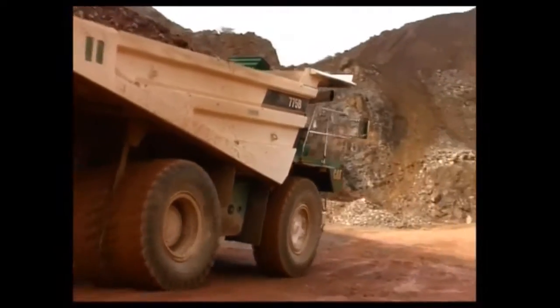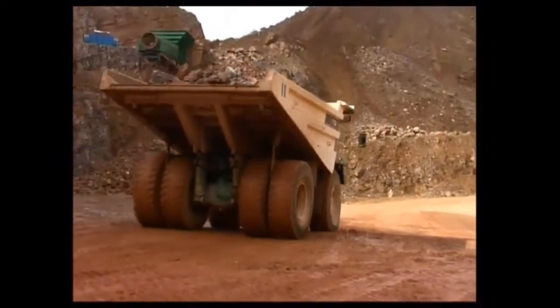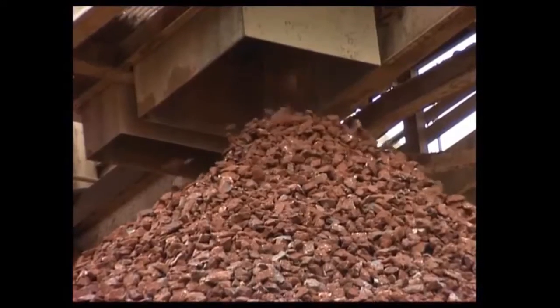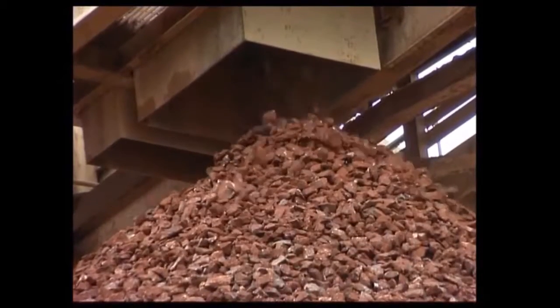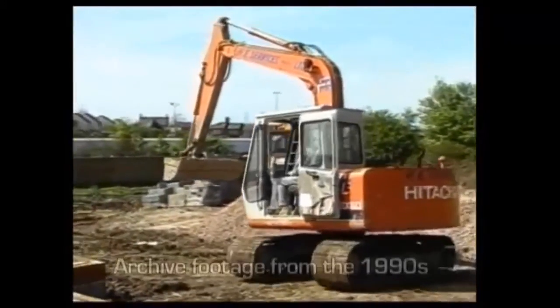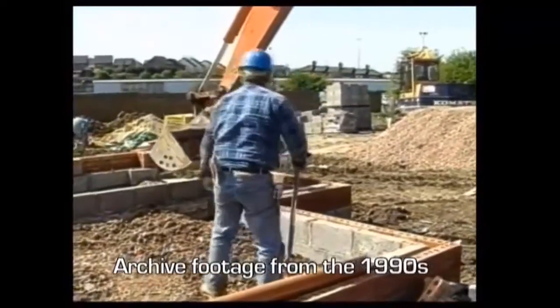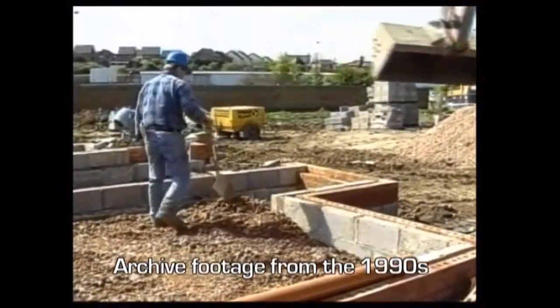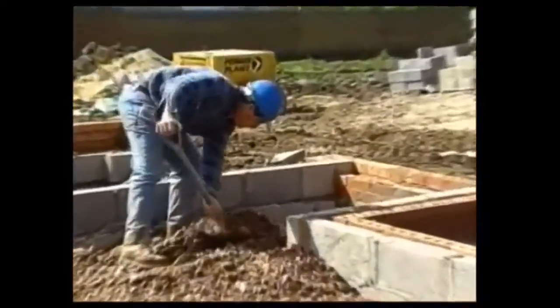In some parts of the country, stone is not readily available and other materials have to be considered. In the past, broken bricks, crushed concrete and various industrial and mining wastes have been used as hardcore. These materials should be used with caution, however. Some may contain impurities, which over a long period can react with water, causing expansion of the hardcore or a chemical reaction in the concrete. Both can lead to cracking and lifting of the slab.